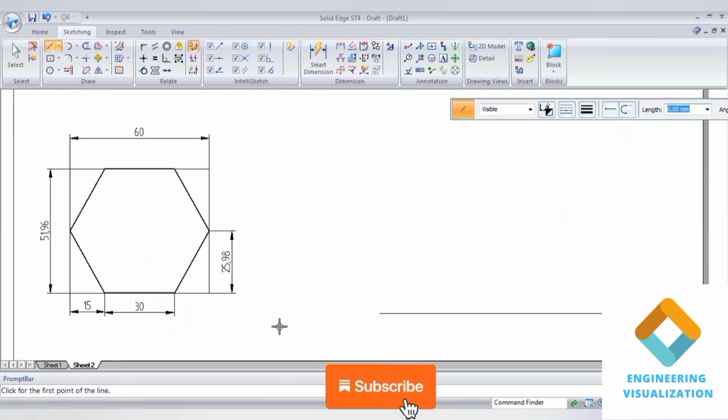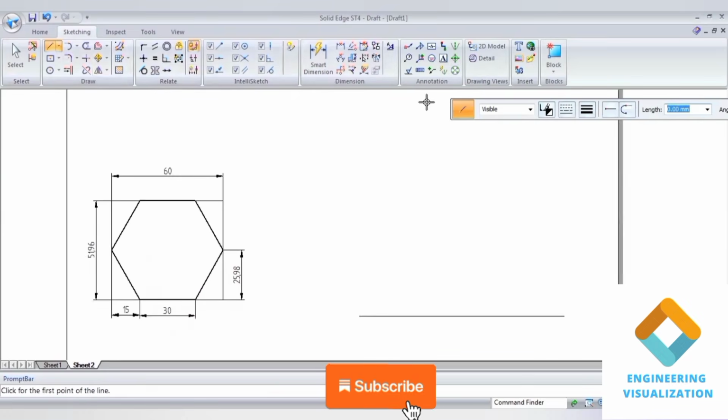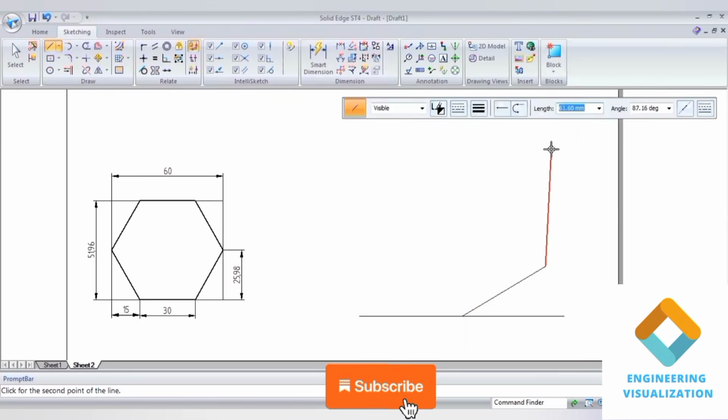Take a reference line. Okay, so from this reference line, construct a box for a length of 51.96. That is the first length, 51.96, and angle 30 degrees. Okay, the second length is 60, angle is 150. Again the length is 51.96, angle is 210. Okay, now join. So the box is constructed.